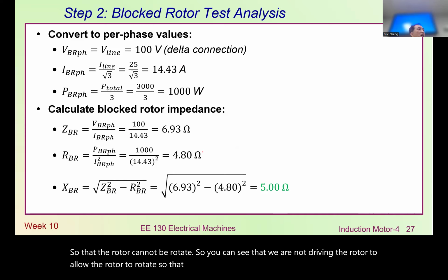So in the block rotor test, we should have some resistance and some reactance here, so the whole path is in here. Now you may ask me, oh, there's an impedance Lm here. Do we need to consider that? Usually when we have lower voltage, the Lm is related to the core loss, so with low voltage and low B field, the core loss will be small. That's why we use low voltage for this kind of block rotor test, so that we can ignore this component. And then the whole loop here looks more like this loop of the connection. That's what we're trying to do.